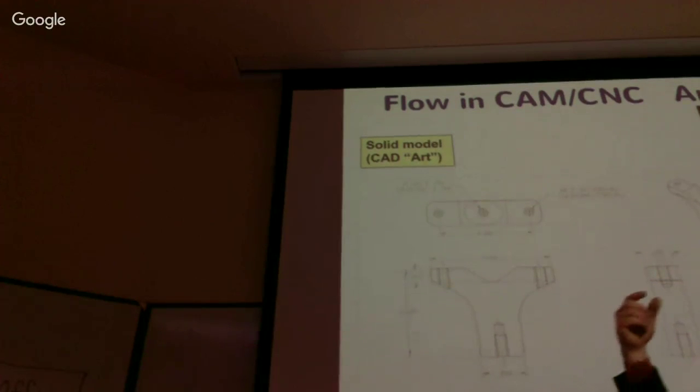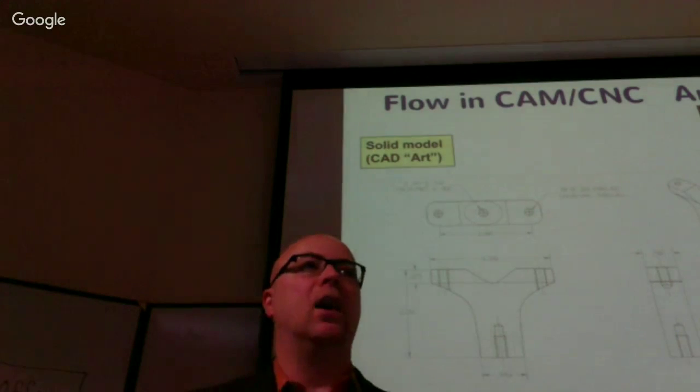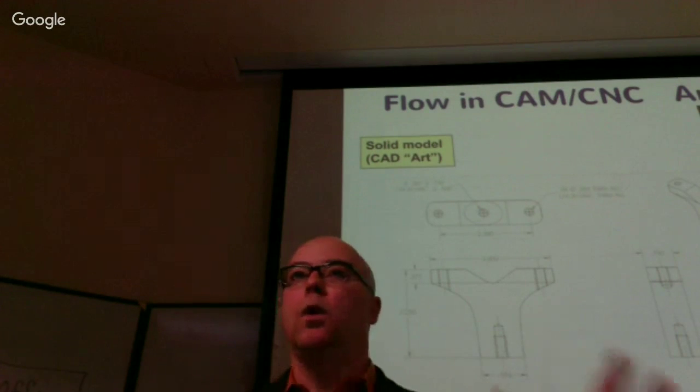And so if you were going to turn something like that, the tool would have to move in and out super fast because we spin at like 2,000 RPMs, 3,000 RPM. So the tool for each revolution would have to do one of these, actually two of those, right? Because two halves of the part. So we typically don't turn something that's not perfectly cylindrical at the end. Not saying it's impossible, but it's certainly expensive. So we won't turn it.